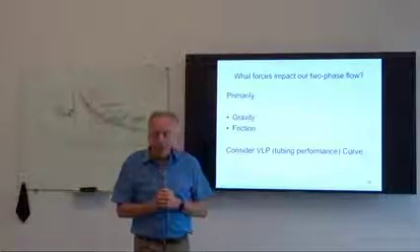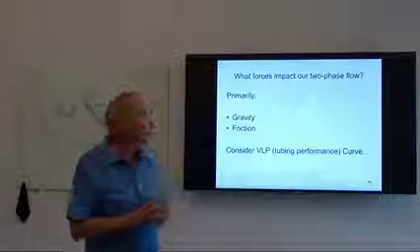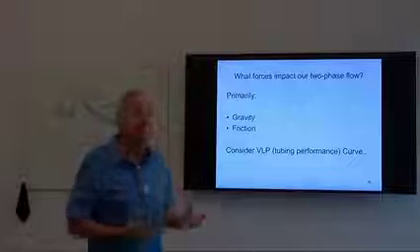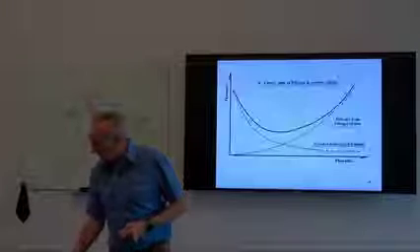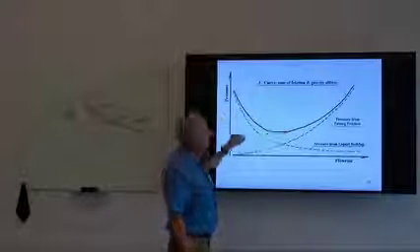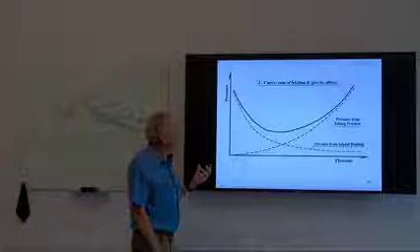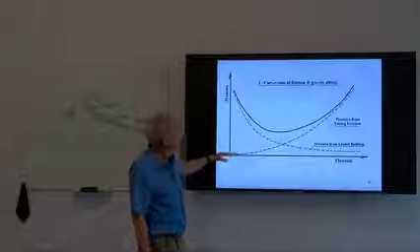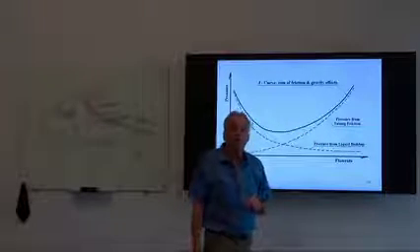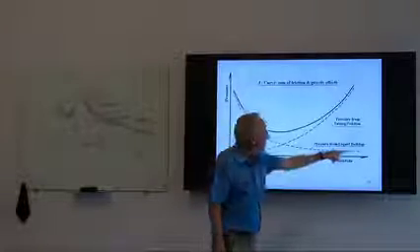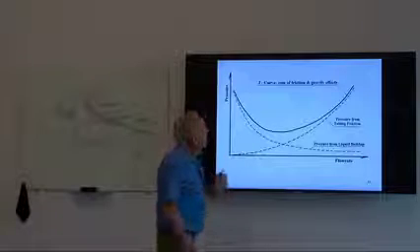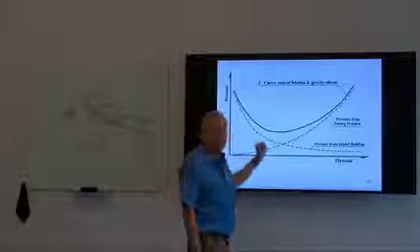With nodal analysis, we can create what is called a vertical lift performance or tubing performance curve, sometimes called the J curve. It is represented by this solid black curved line, and it is the sum of this particular curve here, which is the pressure from friction in the tubing, added to the pressure from liquid buildup, or the hydrostatic load. So we have these two elements, which are the key contributors.